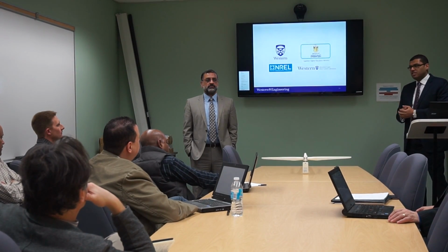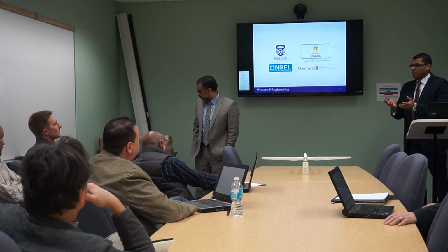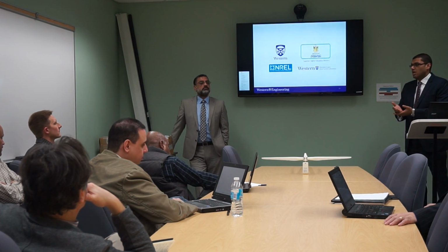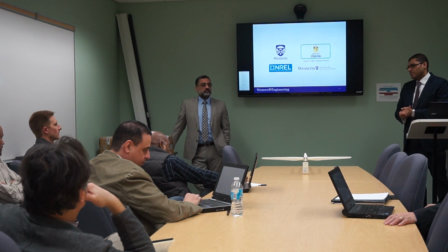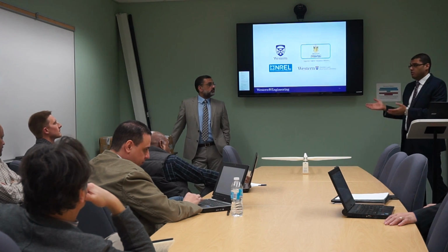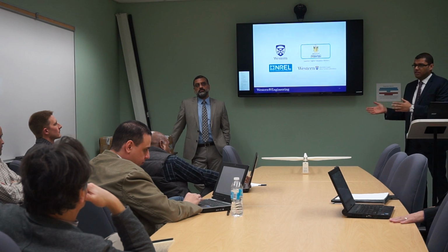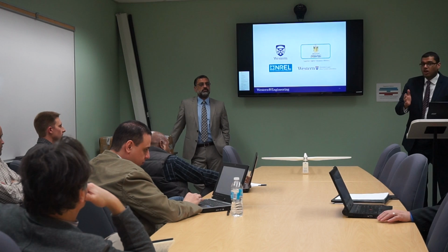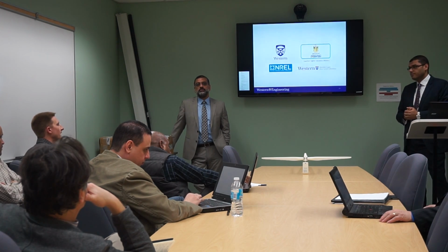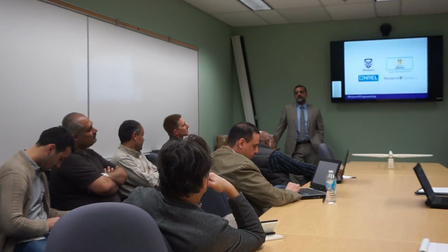Although, as we said, there is some simplification in the analysis. For example, as we said, there was no accurate wind load. So if you just increase the load to be on the safe side, you have a larger factor of safety. And as we have seen here, we can use a smaller pile diameter by just adding the plate to be the same or better performer than the 6 meter diameter. So you're already using a larger factor of safety. Okay, so I guess the follow-up question is, does the current system work?